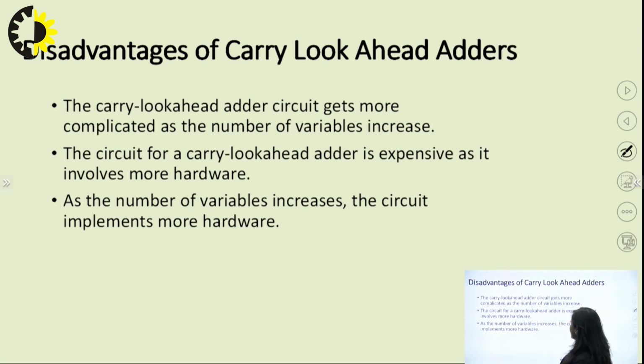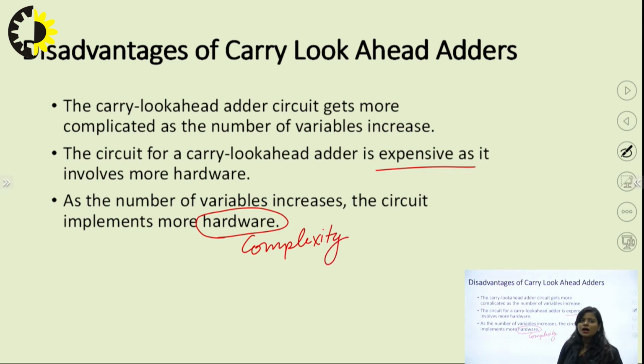The circuit for a carry look ahead adder is also very expensive, because it involves more hardware, which is difficult to deal with nowadays and involves more expense. So as the number of variables increases, the circuit implements more complexity, more complexity to handle.